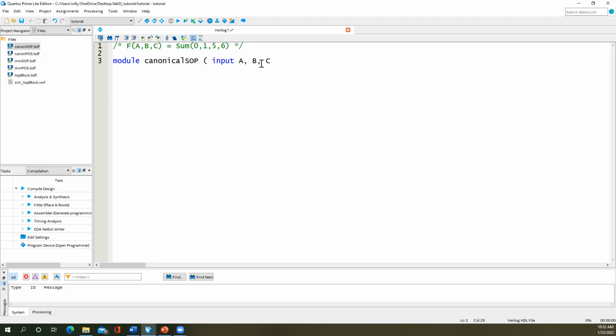In other words, if I just say input ABC, it's going to make the type wire. There are other types in Verilog, such as int, reg, float, other types like that are more advanced uses. I always encourage my students to say input wire so that they realize that this is a wire type as they're learning, right? After that, right, you specified the signal names. Notice then I separated them with commas. So A, B, C. You don't have to have the spaces. I'm doing that here for readability. So everything I keep typing after this would be assumed to be an input. And it is 1 bit by default. If we don't specify size, and we won't this time, all of our inputs are 1 bit. In other tutorials, we'll show how to specify size.